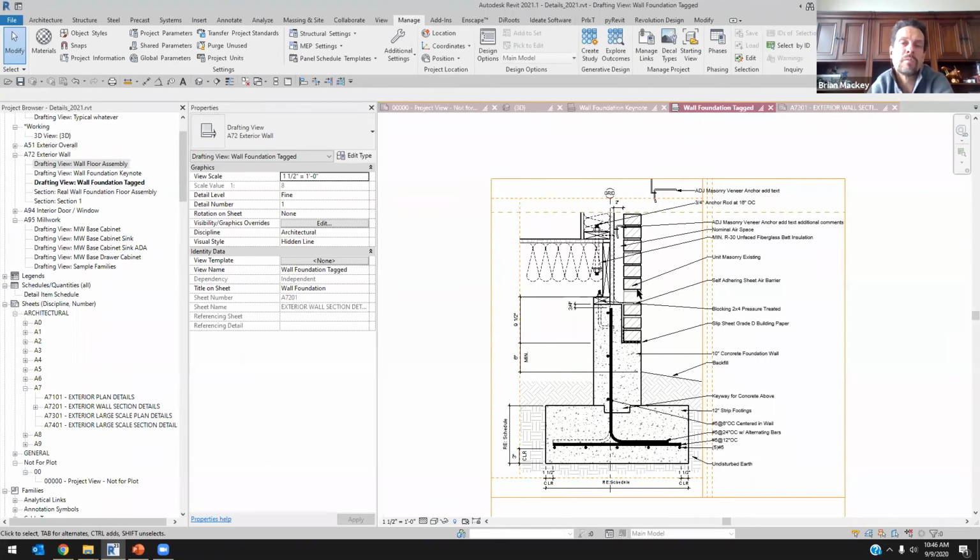You're going to get all of those components repeated, and the reason for that is Revit does not see the information. If Revit sees the families as a different save, so on the project, if it has a different save date than the one on your server or the one you're copying it from, Revit will create duplicates. One of the ways around that is to load all of the detail components from your server into the file you're copying it from and into your current project. Then it'll see they have the same save date and it won't go through and duplicate those.